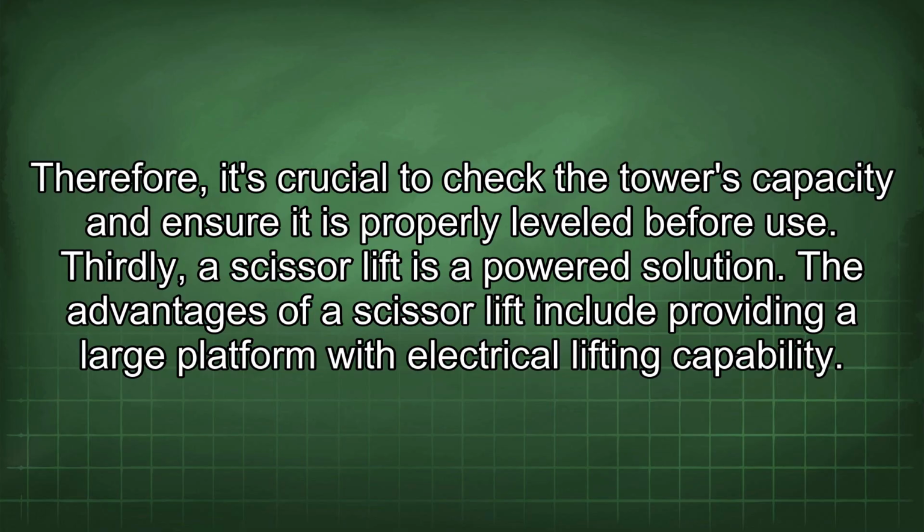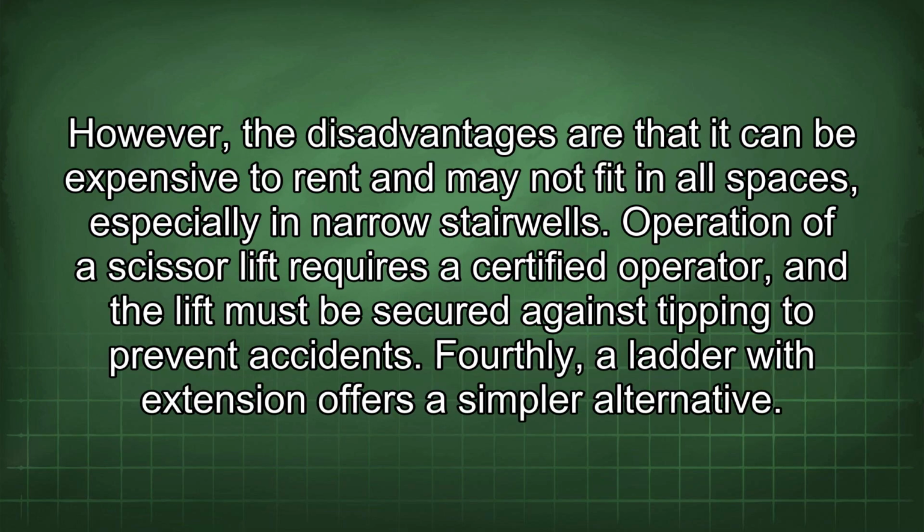Thirdly, a scissor lift is a powered solution. The advantages of a scissor lift include providing a large platform with electrical lifting capability. However, the disadvantages are that it can be expensive to rent and may not fit in all spaces, especially in narrow stairwells. Operation of a scissor lift requires a certified operator, and the lift must be secured against tipping to prevent accidents.